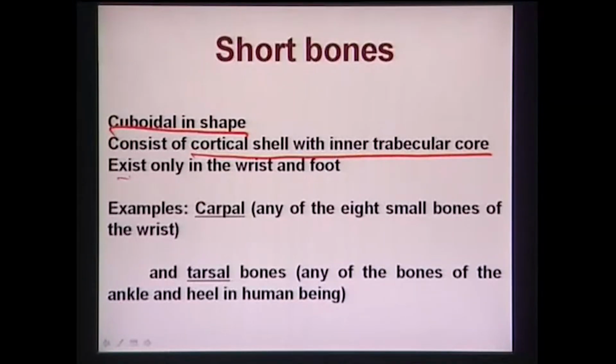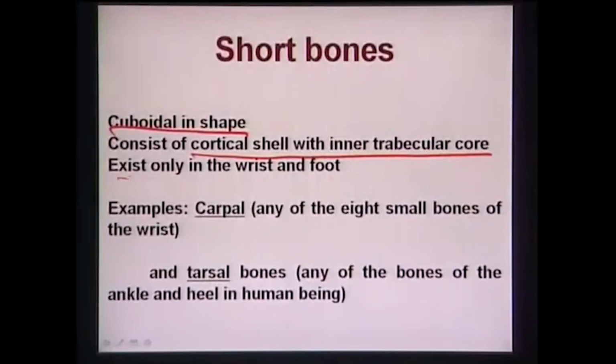inner trabecular core. So typically what you see, generically bone always contains a cortical shell, that means the hard surface, and the hard surface actually protects the internal part of the bone. So that is the reason this concept is very natural. That is the reason people always put coatings on the surface. Coatings are typically harder than the substrate. So whenever you put coatings like titanium nitride coatings on titanium or some other examples, titanium nitride has much higher hardness, much better wear resistance than the titanium.